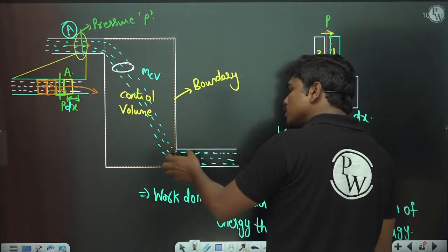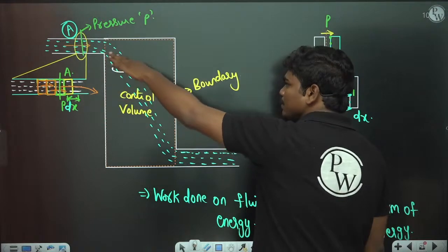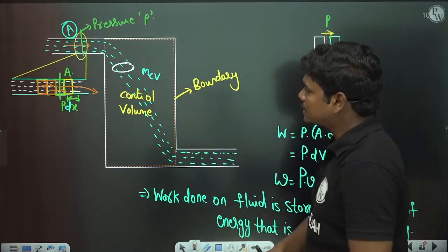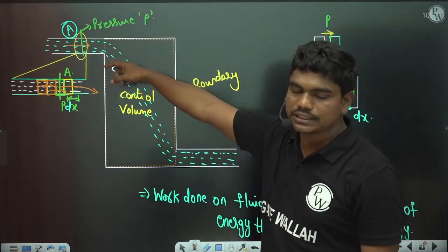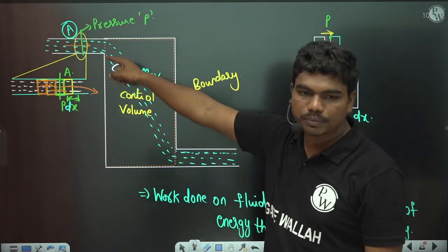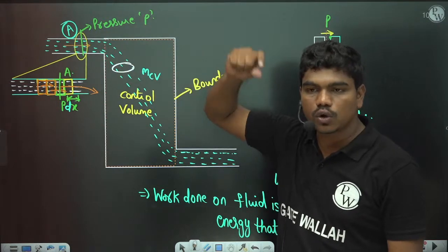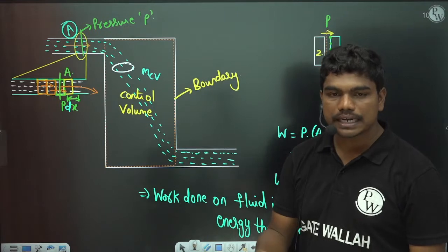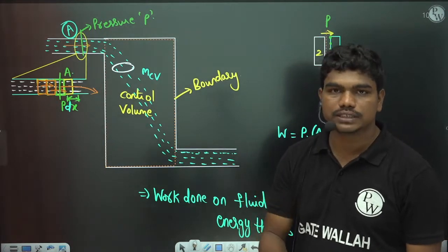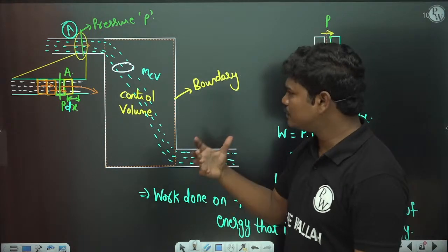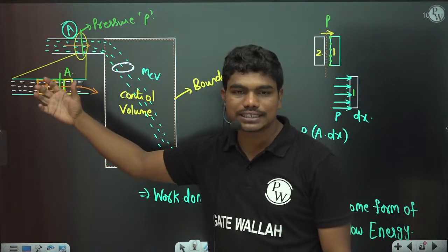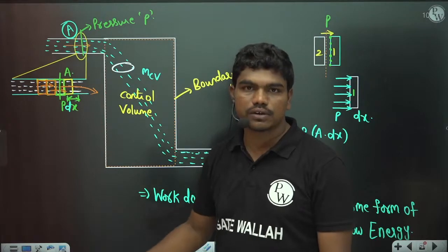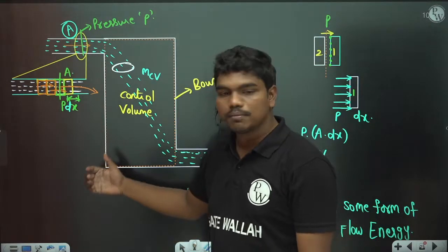Here also the potential energy will still exist, because the potential energy is also defined at any instant, but this stored form of energy which doesn't change generally in this case is U plus PV. So this combination, the total stored form of energy, is called enthalpy within any system in general. That's why we define enthalpy with specific terms always, U plus PV. Very few times we write kinetic energy and potential energy as intensive terms, but we always denote enthalpy as specific enthalpy when we are talking about properties.